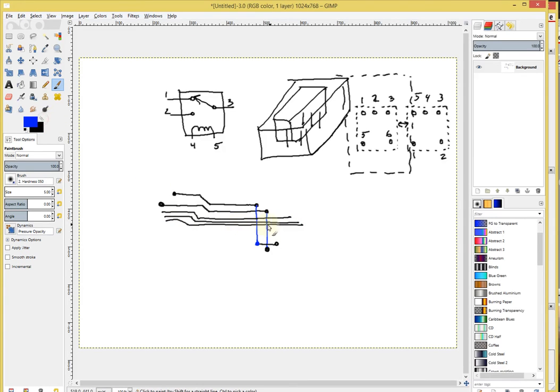And then in the other layer, I can go ahead and lay out traces in this direction, and I never block myself out, because you have these separated into two layers. If you don't do that, you are bound to eventually run out of room. If I do this, and then you connect these two pins, and then let's say you needed to connect these two pins, you're out of room. Either you will have to come way around here, assuming that you have any room to move into, or you may be completely blocked. Suppose I have another pin, what do I do next?